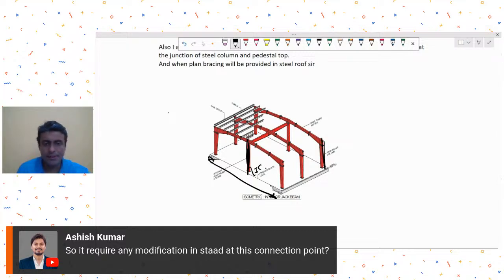Again, in this span you have got the internal column. Now, for some span you wish to not have an internal column because you wanted a column-free space over here. So what you do is you provide this element. This element will be column to column, and then on this element this rafter will be supported. So this is called a jack beam. I hope that is clear.